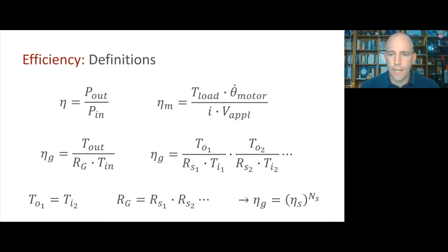Now, how do we characterize overall efficiency experimentally? Well, the way to do it is to apply a known output torque, say by hanging a weight of known mass off of your capstan of known radius, and then measuring the input torque from the motor. And the way you get at that is from that torque balance. We have that this input torque from the motor, that'll be the load torque. It's just going to be Ki, I we measure, K we've characterized, minus tau fric, which we've already characterized.